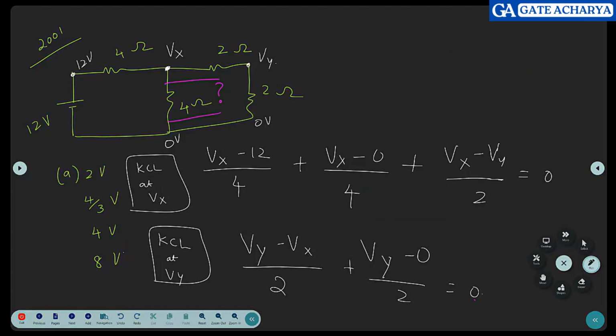This is one way. You can write two loop equations. I'm going to do that also. Of course, you don't need all these things. You can just reduce the resistances, find the current. I'm just giving you an idea that you can do all these things. How to write these equations? See, for a simpler problem, you don't need these equations. You can just reduce all the resistances, make it a single resistance, find the current, divide the current, it's done.